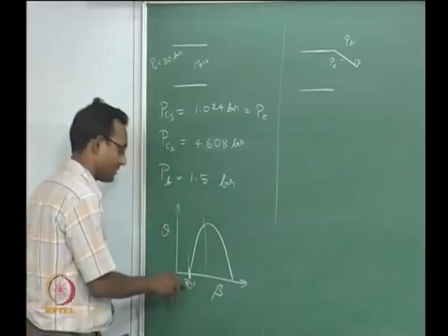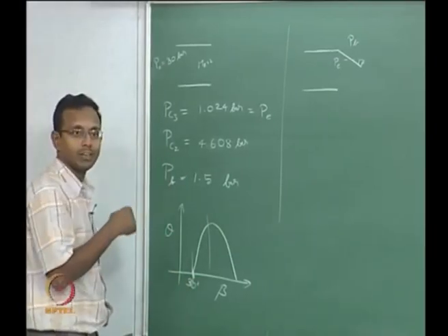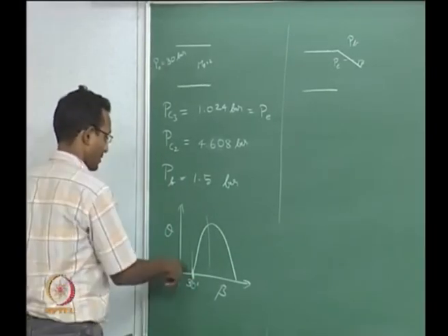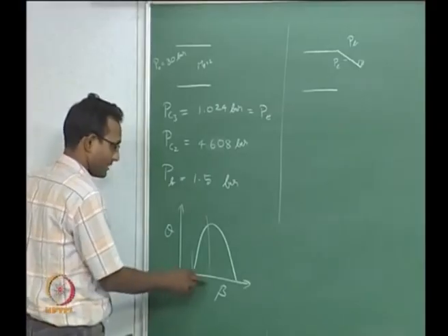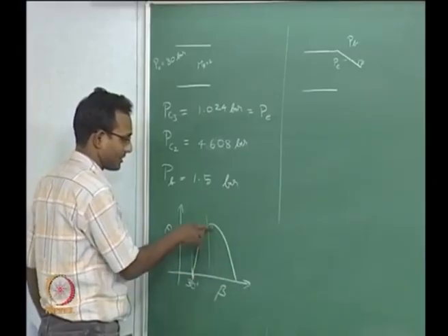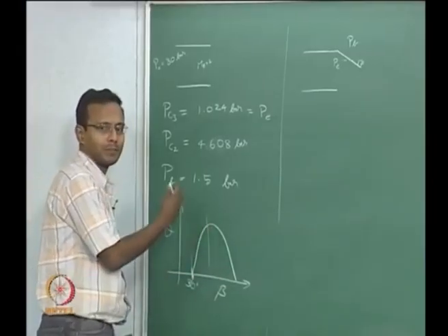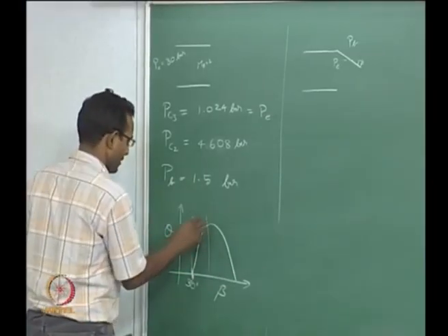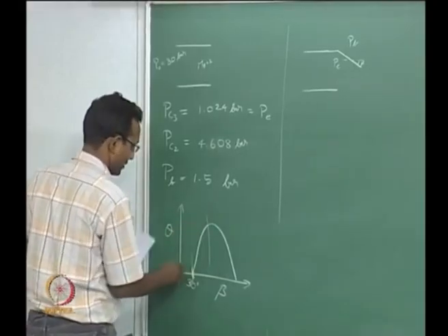How do you know that? That is the sine inverse of 1 by 2, where 2 is our Mach number. That is your Mach angle, and so I want to guess some value inside here. If you go look at the Mach 2 condition, the peak value will be around 63 or something. We won't worry about that. Currently we will just look at numbers as something in between.